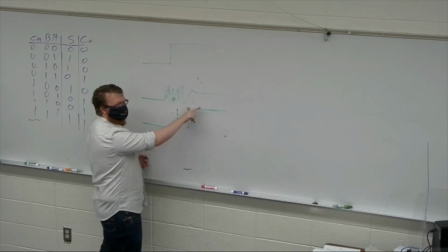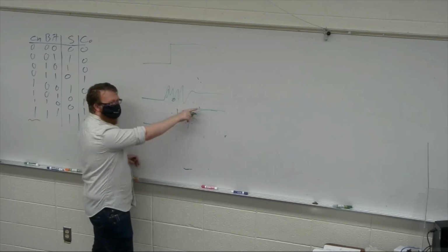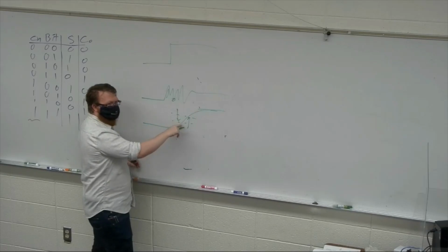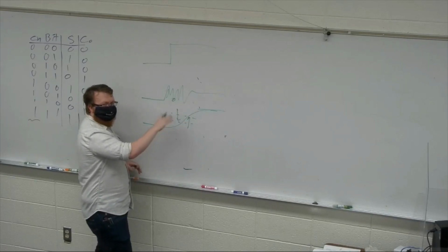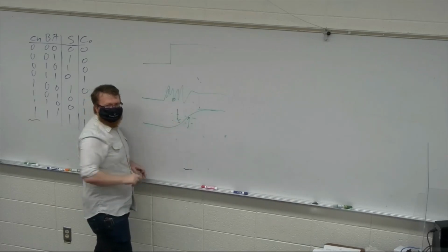Over this threshold to go on, under this threshold to go back off. This is kind of an ideal situation because once I cross that, I'm never going to come back under that. But if it's flipped and there's this kind of no man's land, I could literally end up with some internal oscillation because the comparator doesn't know what it's supposed to be.